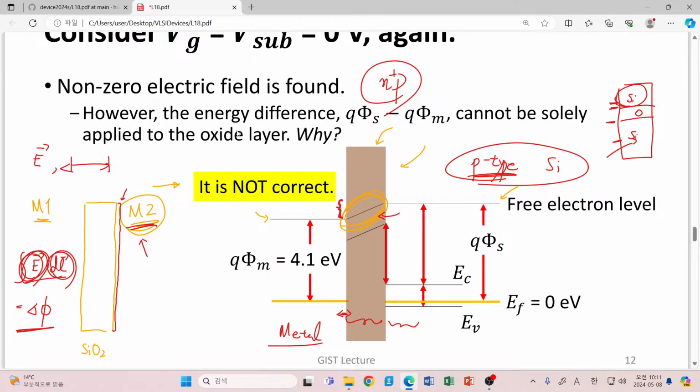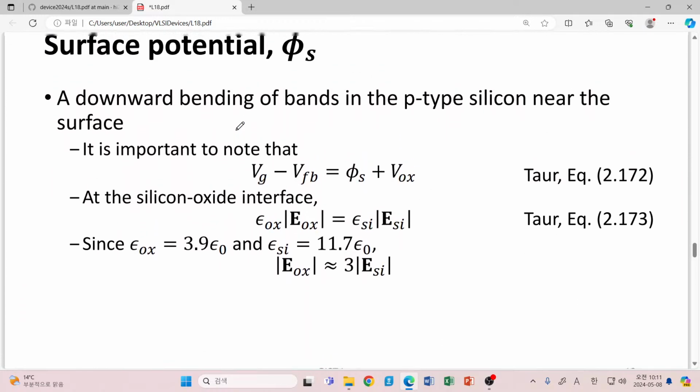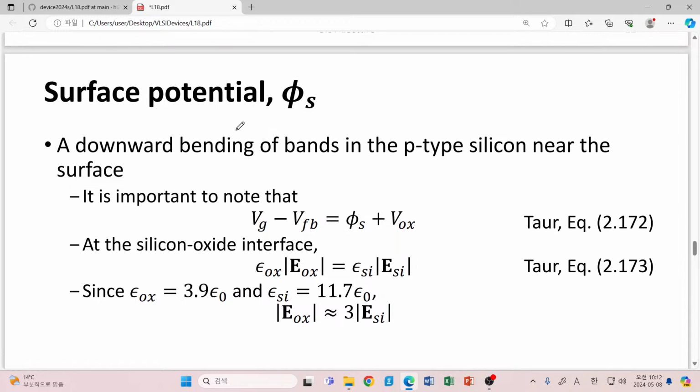It needs a certain distance, because the mechanism for neutralizing that incoming electric field is just depletion of our mobile carriers, so we need a certain distance. Okay, I think this is the most important thing to understand MOS behavior, and amazingly enough, it can be simply written in this amazingly simple form. So if you understand this one, then I think that it's really good.